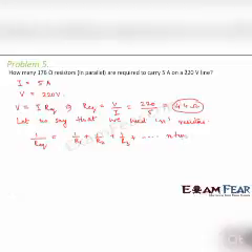N times, because I say that there will be n resistors. Now the value of each of these resistances is 176 ohms. That means their values are same. So we can write 1 by R plus 1 by R plus 1 by R. So how many times? N times I will add. So I can write it this way, that 1 by R equivalent is equal to n divided by R, because adding 1 by R n times means multiplying 1 by R with n.